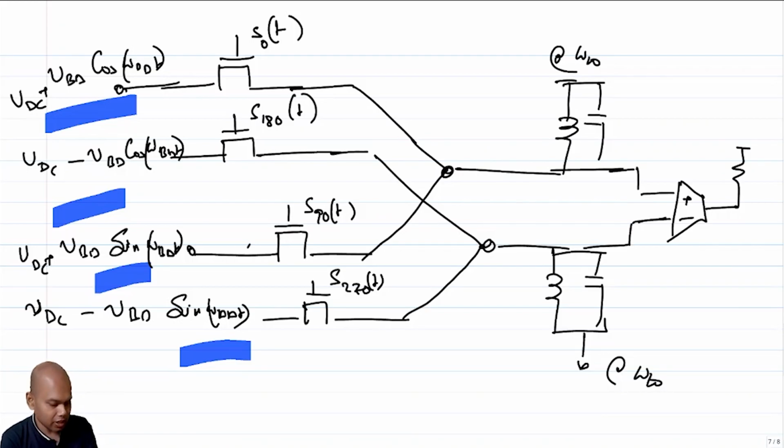So if this is a voltage driven source and these switches are only acting as switches, obviously, then if you simply connect it like this, what are you essentially assuming? We are assuming that the impedance looking this side is much smaller than the impedance looking into the load, right?